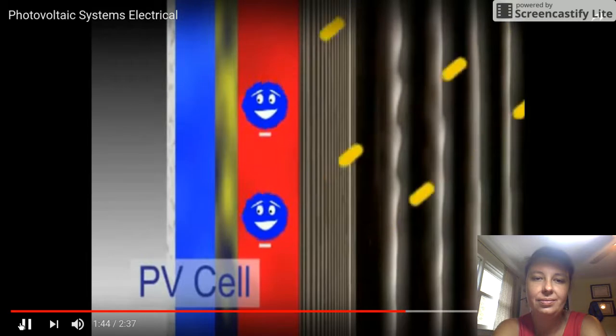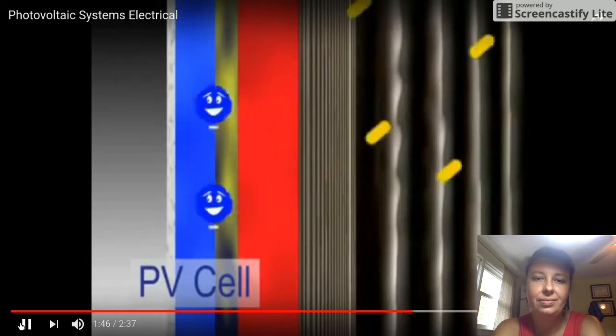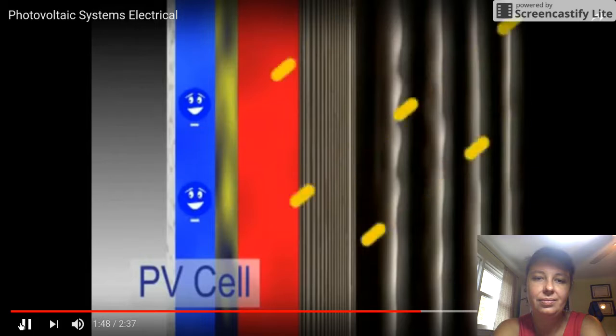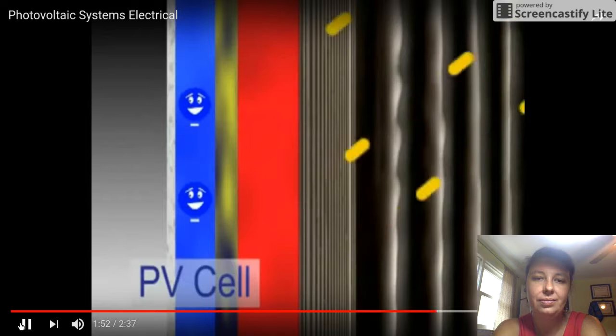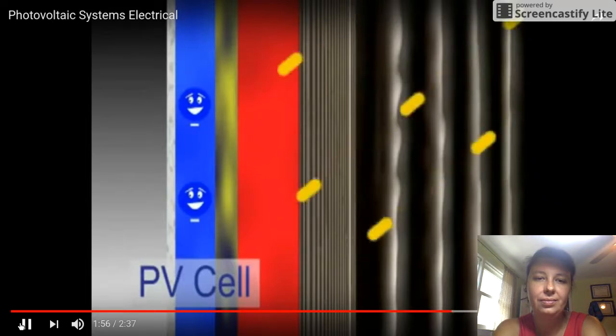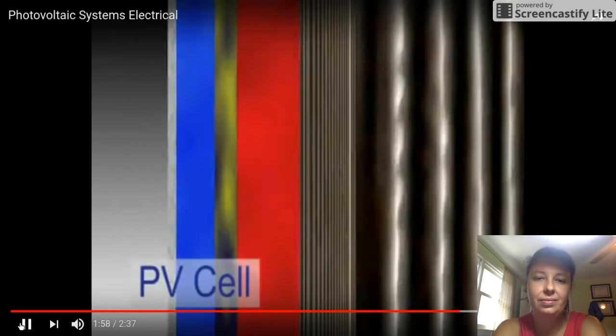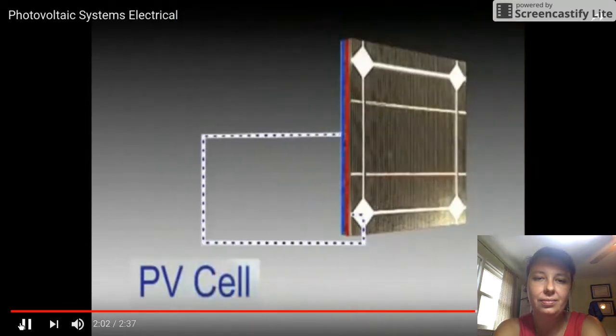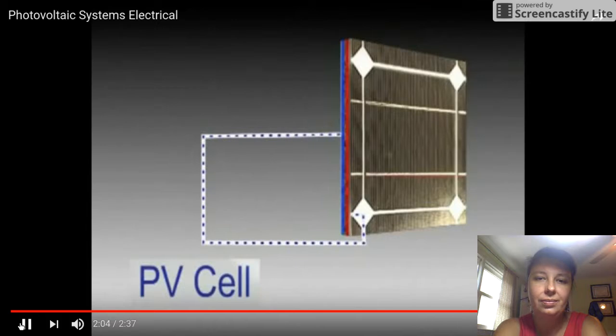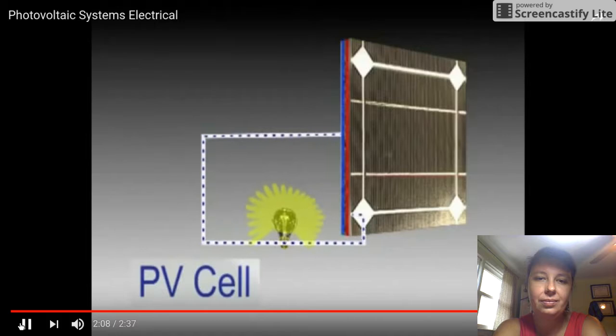Some of the energy absorbed will be transferred to electrons in the cathode, giving the electrons the energy required to cross the junction and reach the anode. But once the electrons have arrived at the anode, they can't return to the cathode directly across the junction. Instead, they must flow through an external circuit in order to return to the cathode. As the electrons flow through the external circuit, they can give up some of their energy obtained from the light photons to devices in that circuit.